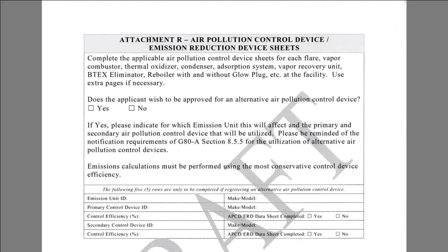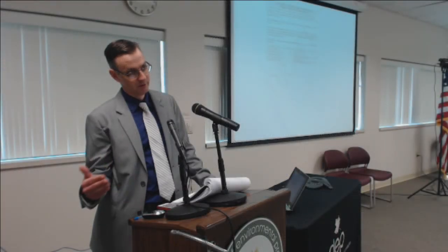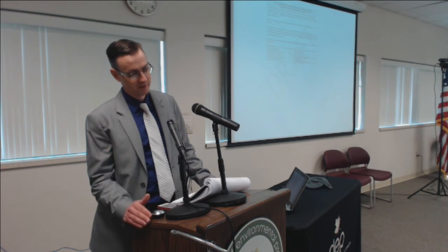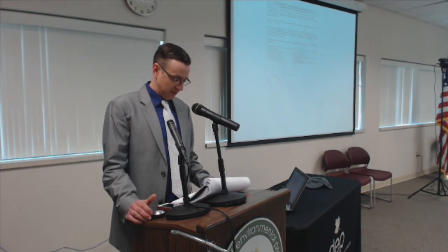And you also must conduct your emission calculations with the most conservative. So like if using one air pollution control device, your VOC emissions were 5 tons per year and the other one was 8, then your PTE has to be calculated on the 8. Your facility-wide PTE would be calculated on the 8 tons per year. So that way, you know, that's worst case scenario. So that's how your PTE would be calculated.